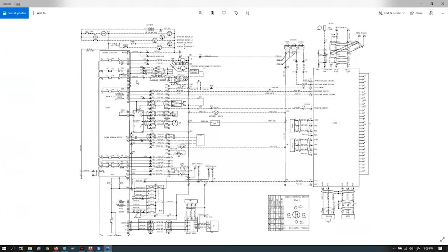And if you remember on the first schematic that I brought out, I circled right here in the center and said, oh, look, there's a module. Well, in this schematic, here's the same module, but now not only do we see connections on the outside of the module at different locations, but we can see some internal components and even some relay logic inside that module. So it's much better for troubleshooting purposes.